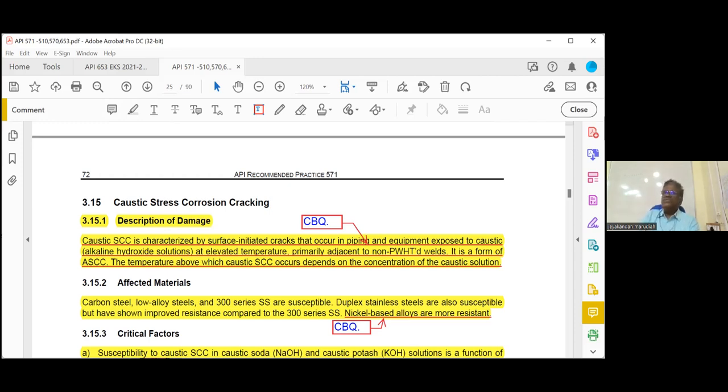Now, for surface cracks, which NDT will we do normally? MT, PT. But please remember, PT is not preferred for stress corrosion cracks because of the corrosion. The corrosion product will fill the crack, so the penetrant will not go in. So PT should not be used as the only method. The preferred method is wet fluorescent MT.